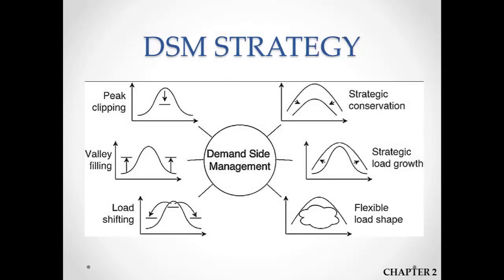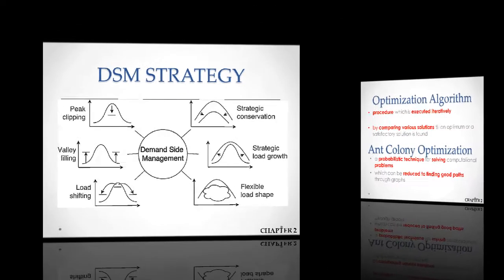With the load profile sample, we must set a strategy to reduce the electricity cost. There are 6 types of DSM strategy that can be proposed, but I am focusing on the load shifting method. This method is about shifting the high energy consumption to the off-peak zone that has a cheaper cost rate. The important factors are what appliances can be shifted and what percentage of load is suitable to shift.